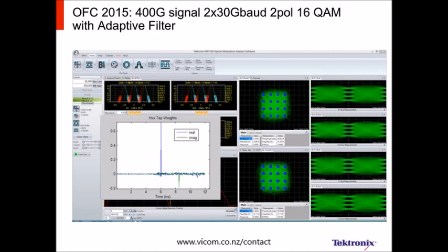What adaptive filters do is they basically design an FIR filter that corrects for whatever frequency domain impairments are found using some sort of feedback method, either looking at the amplitude of the symbols or looking at the position of the symbols in, say, a decision feedback loop. But anyways, you end up with a filter, and that filter can tell you something about your system.